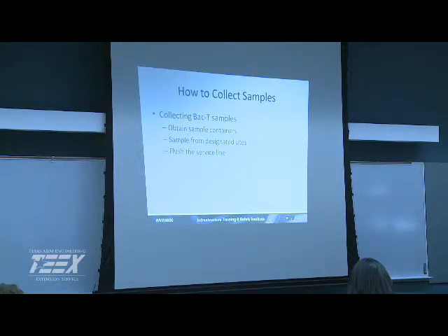You know, coming out of a lab, you got to prove that the number you have is a valid number. And how do you do that? It's your quality assurance and your quality control program. And it's not that difficult with pocket colorimeters and all to have secondary standards and be able to calibrate your instrument fairly regularly. And always follow the manufacturer's recommendations on how often you might need to send it back or when it needs to be replaced. Some will have a certain service life, things like that. So